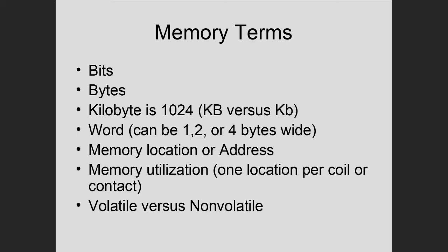Well, it turns out that when you store those zeros and ones, remember in the last class I showed you that virtual logical structure I called an input-output image table? Well, what that really is, in memory, is a group of registers. Now, we talked about shift registers in week 1. You can shift data in serially and shift it out serially. That's serial in, serial out.